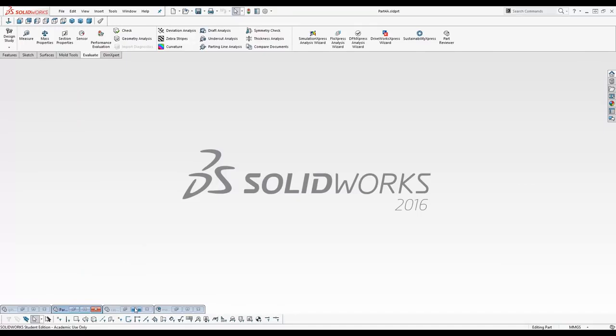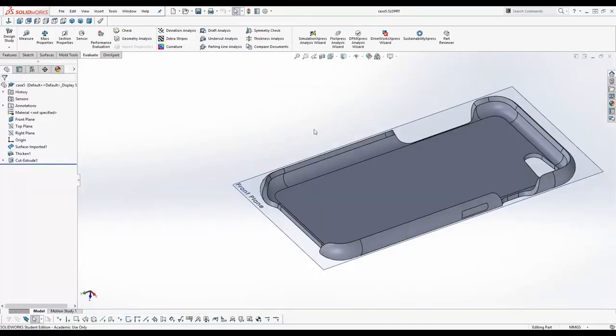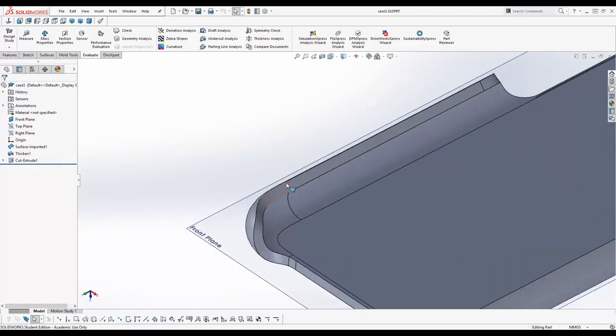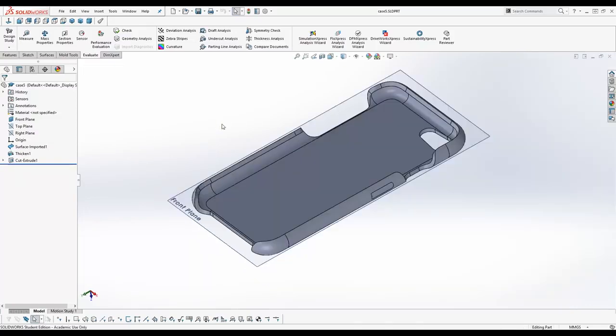From here on you can design the product around the phone. So in this case, quite simple, just some cutouts for the buttons and for the camera. And the product is 2.5 millimeters thick. This is quite thick for a phone case, but we found that this is the minimum for a pressure plastic injection machine. Otherwise you need way more force.